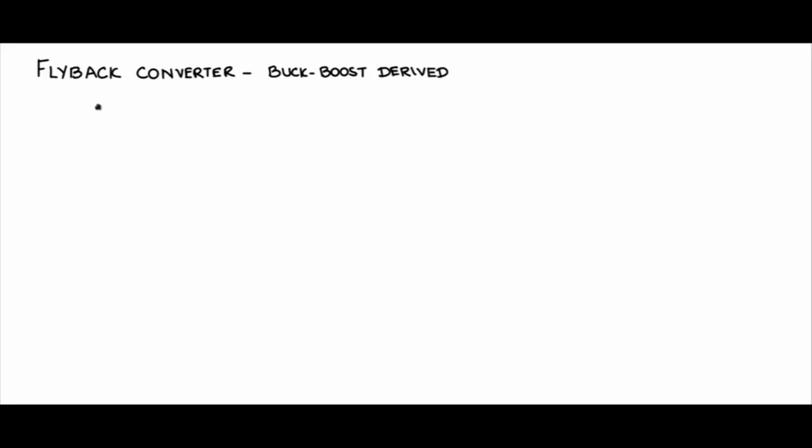Let us now discuss another very popular converter, one of the most popular converters that you will find in most power electronic equipment, that is the flyback converter. It is a buck boost derived converter. The forward converter was a buck derived converter. The flyback converter is the buck boost derived converter. And let us see how the isolated buck boost derived converter looks like.